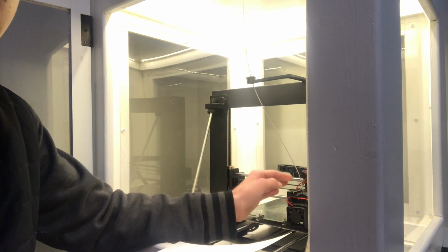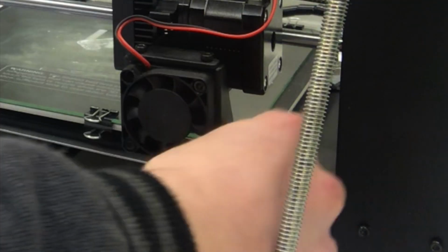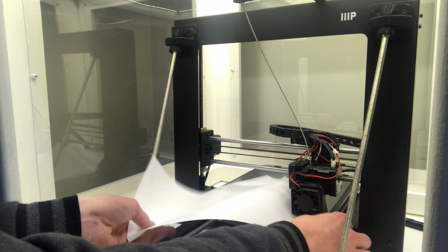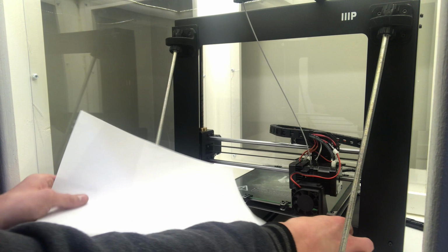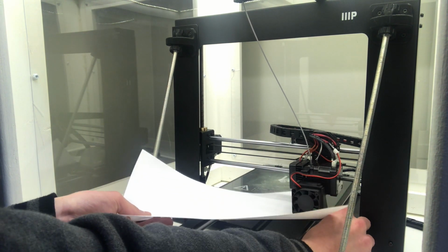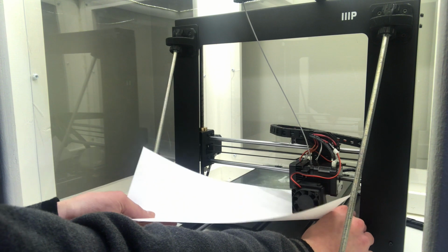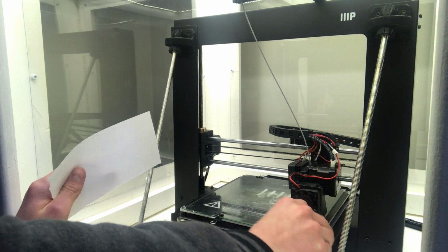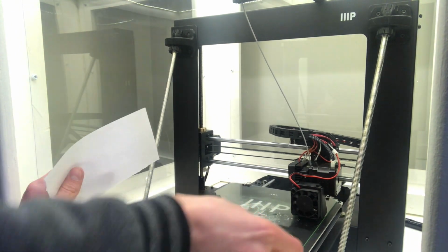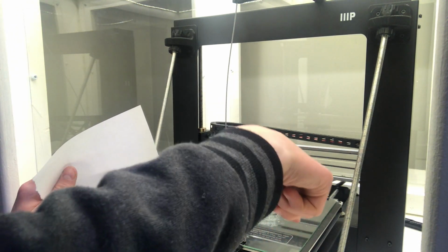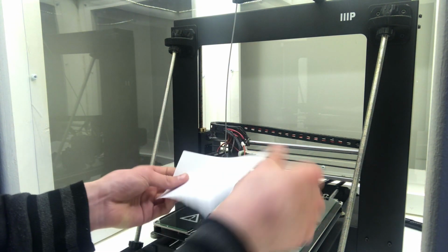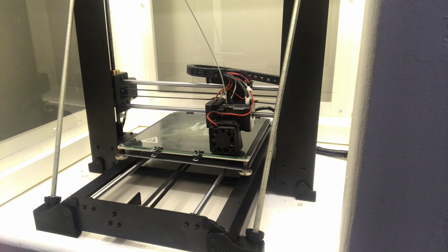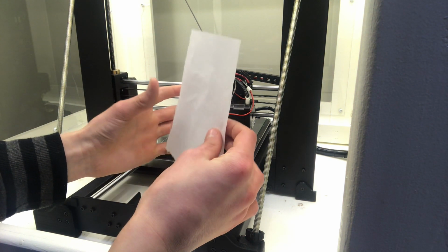You have to disable the stepper in order to move it. If it doesn't go in, there are these silver things. You want to turn those. If it's too tight, turn it, but make sure it grabs and it has a little bit of friction between the bed and the nozzle. A recommended detail, go corner to corner. If you start at this corner, go back here. Once you think you've got it about right, then the next step will be to preheat it.